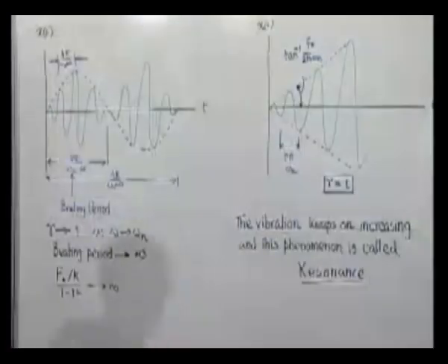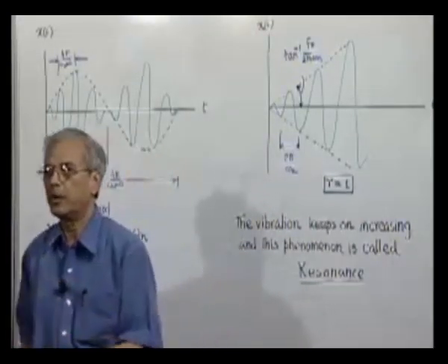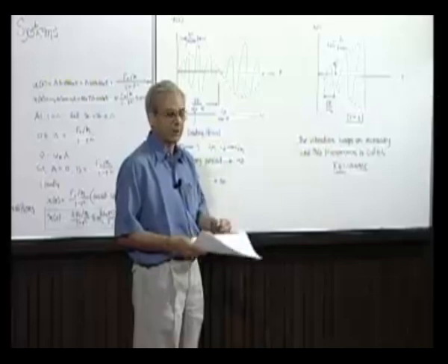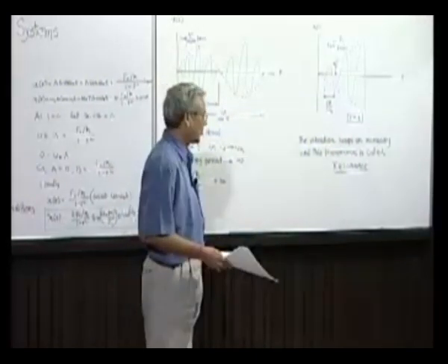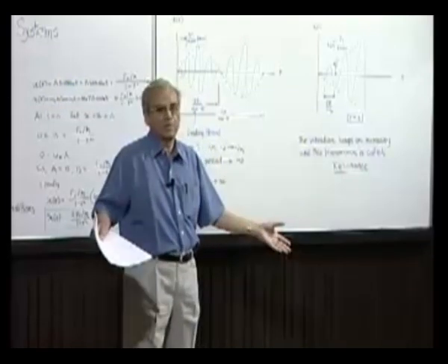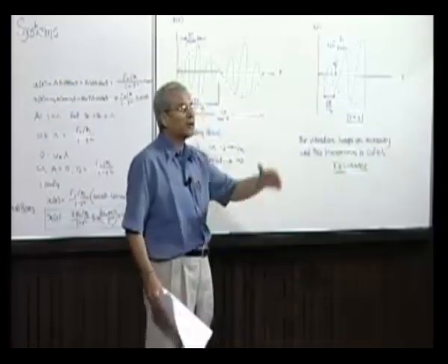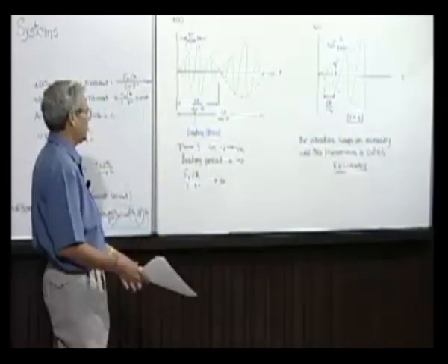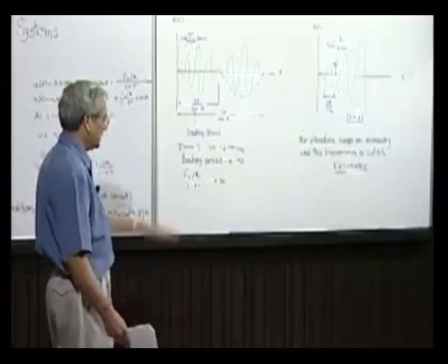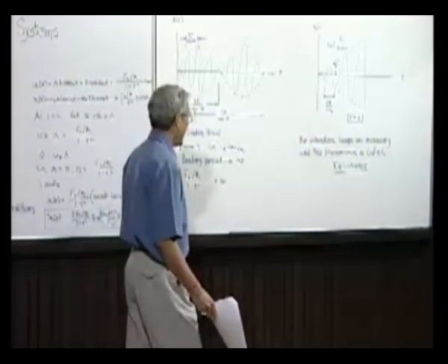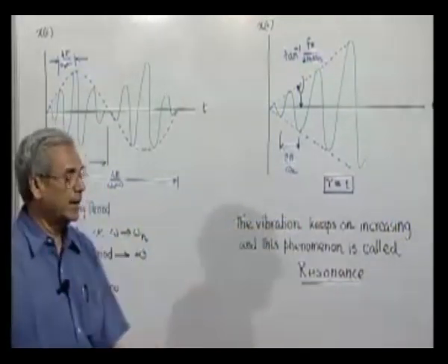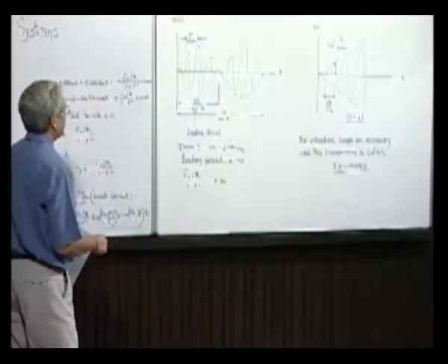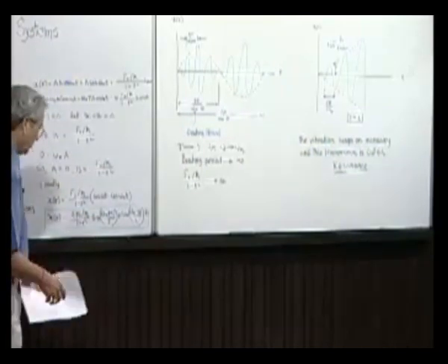These are the kinds of things perhaps you have heard, that when a military marches through a bridge, left, right, normally on solid ground they keep on marching all in unison, that means everybody is in phase. But once they cross a bridge, they are told not to be in phase or unison, and they are not supposed to march, they just walk through. Because in case hundreds of soldiers keep on marching with the same frequency and same phase, the forcing function will be enough to go somewhere near the natural frequency of the bridge, and it can cause disasters. And therefore, this is the point which we wanted to make.